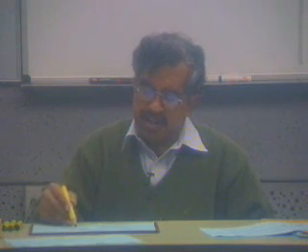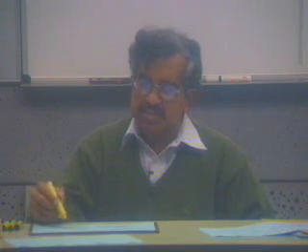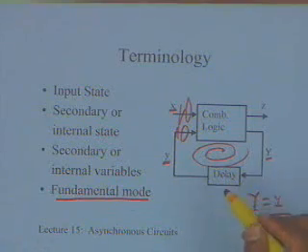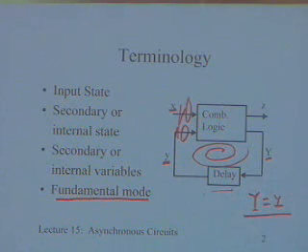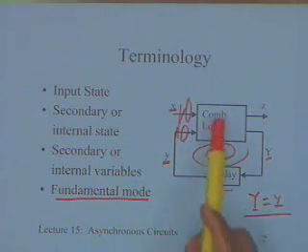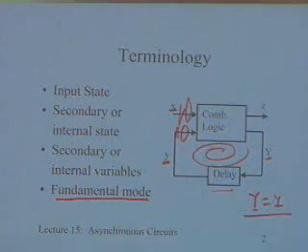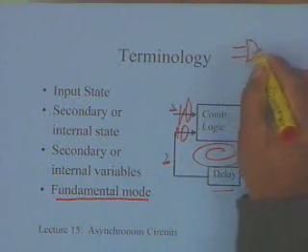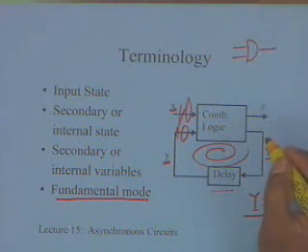Now what is this delay vis-a-vis a synchronous circuit, where we had the state register? What do we have to do to implement an asynchronous circuit? In case of an asynchronous circuit, fortunately, we do not really need any component to give a delay. When you talk of combinational logic, consider any particular gate; I can break down this gate into two parts.